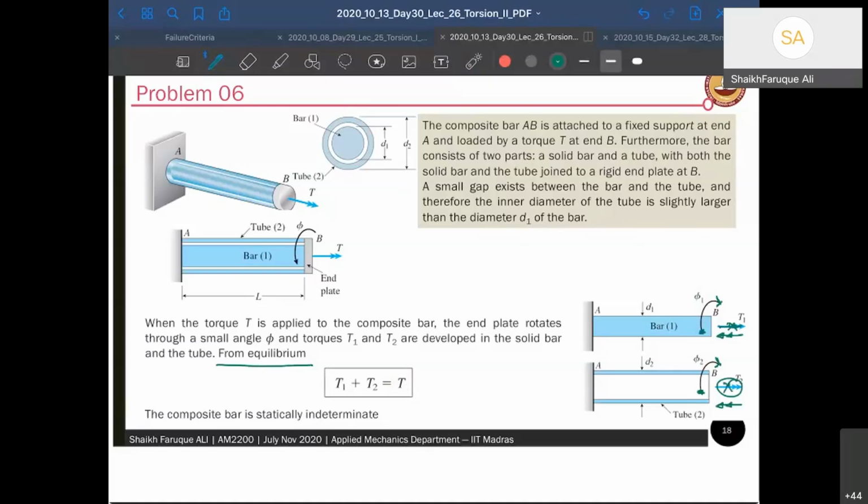Sir, now I think it's Ankit, you have something to say? Sir, actually that was his question, sir. But I'm saying it's wrong, because for plate B, because of the torque T, there will be an opposite torque at the end of the plate, which will give an internal torque acting in the forward direction on the bar, sir. It's trying to pull, I mean rotate the bar. So the bar also turns in the same direction.